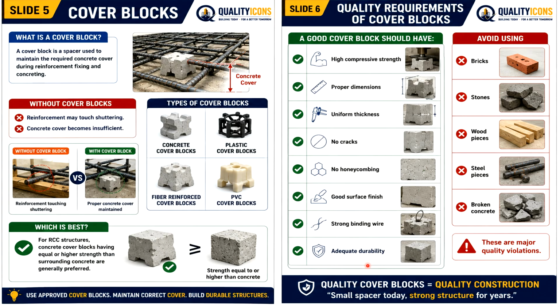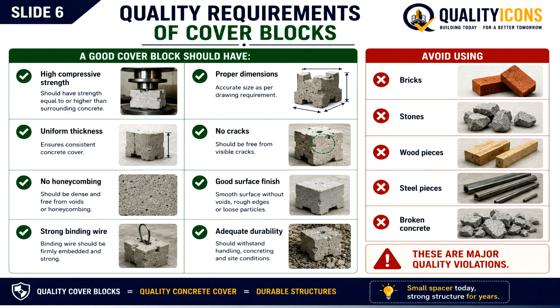This is the most important site mistake. Instead of cover blocks, they are using broken bricks, stones, wood pieces, steel pieces, broken concrete. These are major quality violations. These materials absorb water, change position, or fail to maintain proper cover.